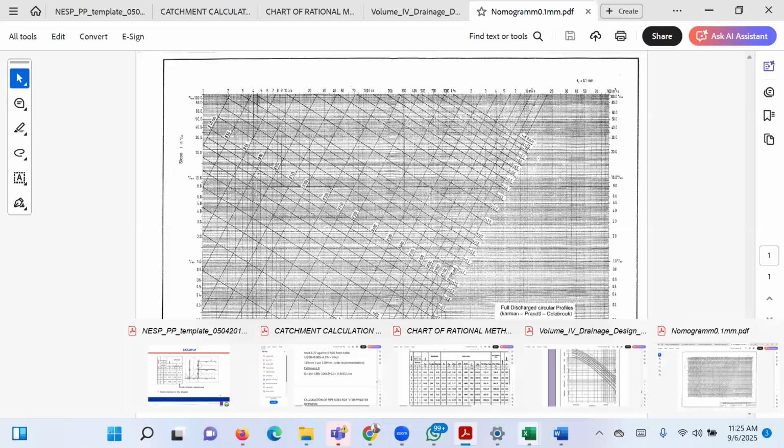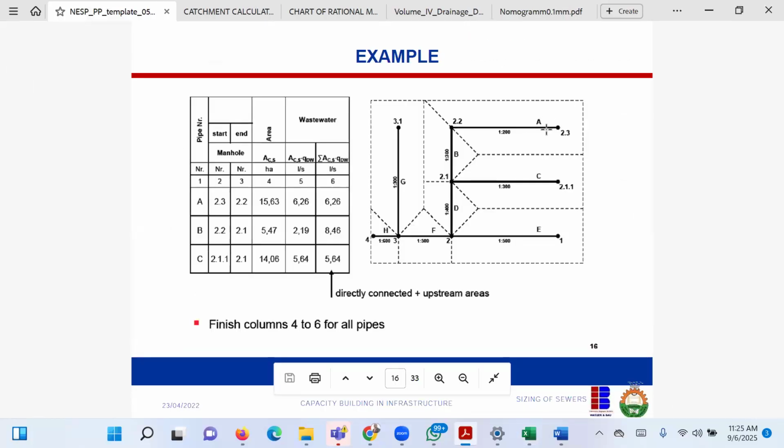So while I will choose a 150 pipe here, as soon as I get here, gentlemen, what pipe size are we using here? We're using 200 mm. This place was supposed to be 125, remember? Here's supposed to be 125. Here's supposed to be 125. But due to minimum requirement, due to code requirements, I'm using 150. But the pipe from D is approximately 150. The pipe from F is approximately 200. Gentlemen, common sense will tell me by the time I go to point H, I've been using maybe 250, but let us do it and see how it goes.